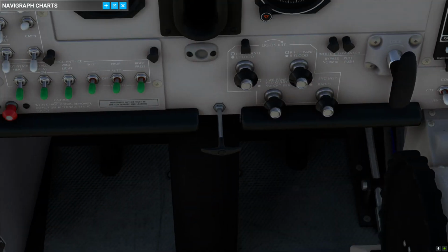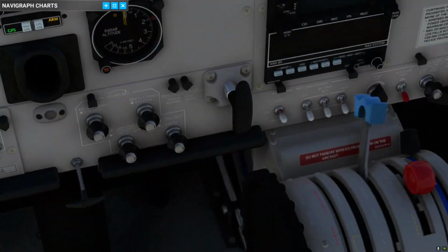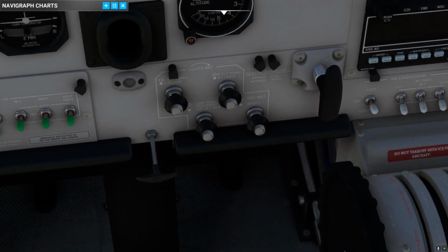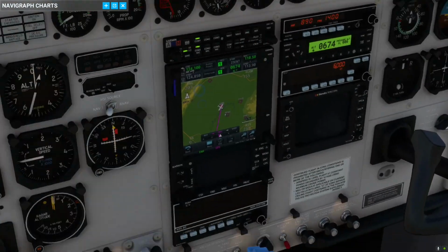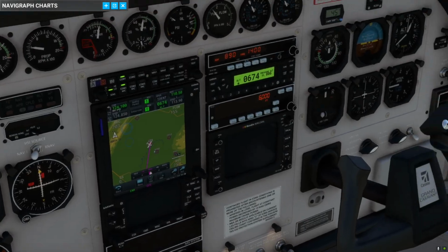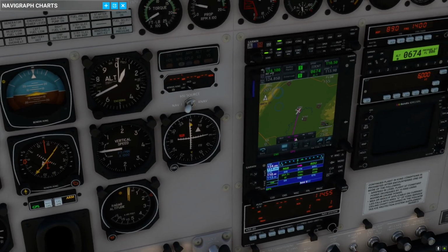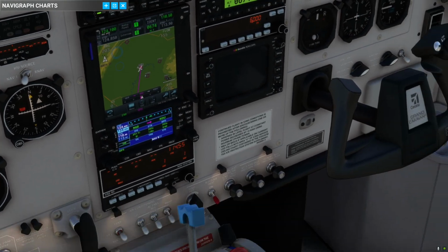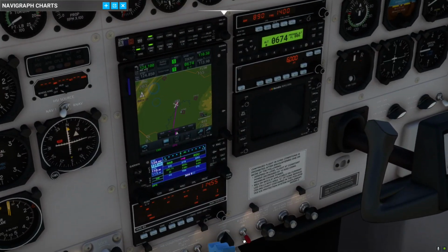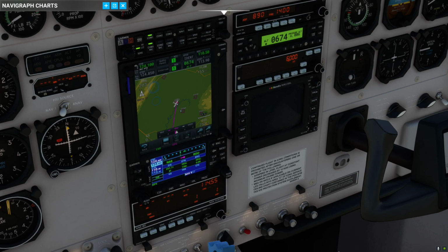We're good. Okay. Beautiful day. No extra lights except for maybe for instruments, and then on the engine instruments. Okay. Make sure everything's readable. Altimeter is set. Second avionics. Don't need the radar. It's chilly. We'll turn on the bleed heat.